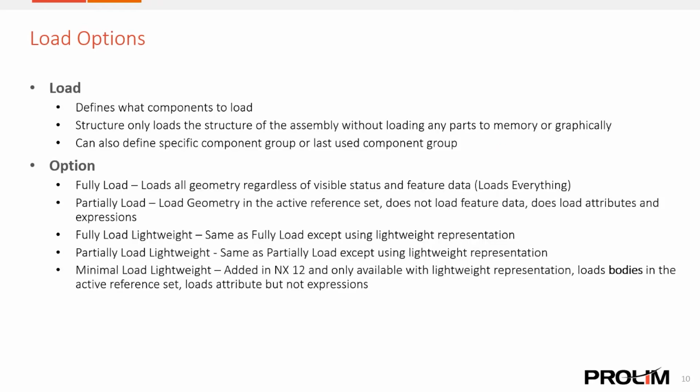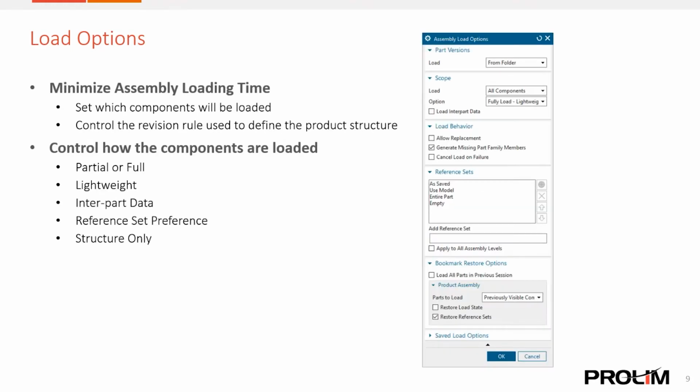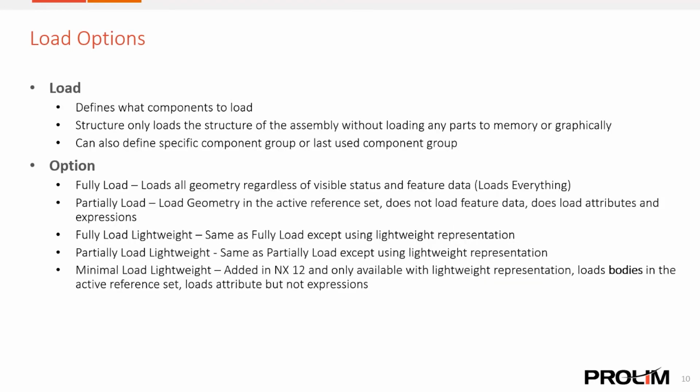Going a little bit more into detail on the different load options, specifically underneath Scope Load, you see where it says All Components. This is where you can define the components that you want NX to load.